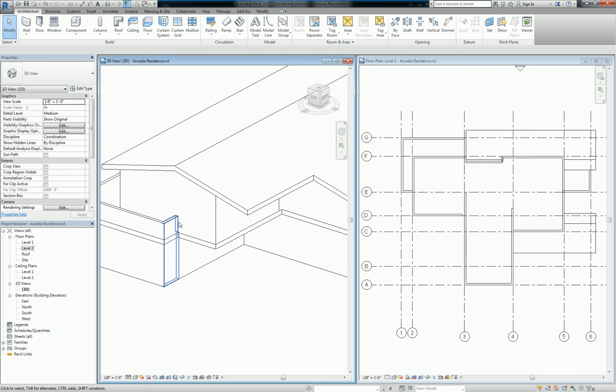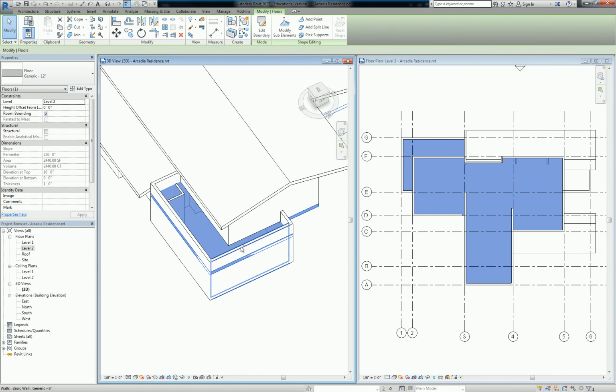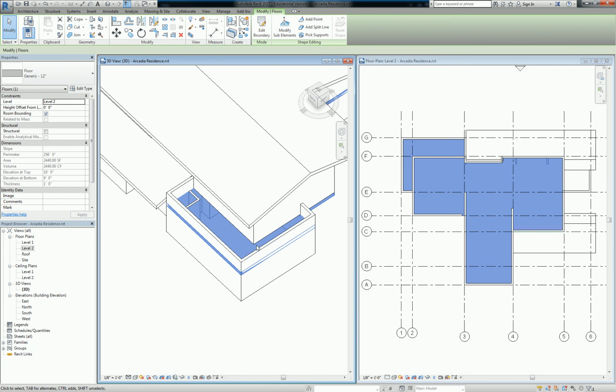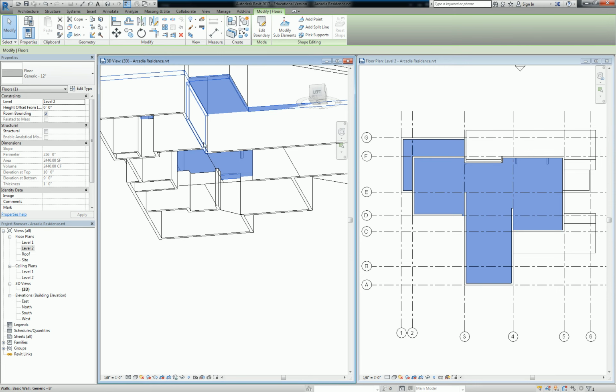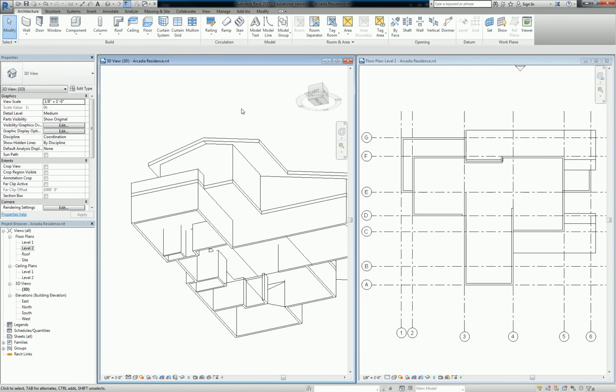Because this is a continuous diaphragm, it encloses the envelope of the building here on the exterior roof assembly, and it encloses underneath the floor on the exterior floor assembly. So that's our goal with that floor plate, is to just create that continuous diaphragm. And when we start getting into detailing and assemblies, we'll discover whether or not we have to modify it and make it 2 separate elements. Okay, is that clear?